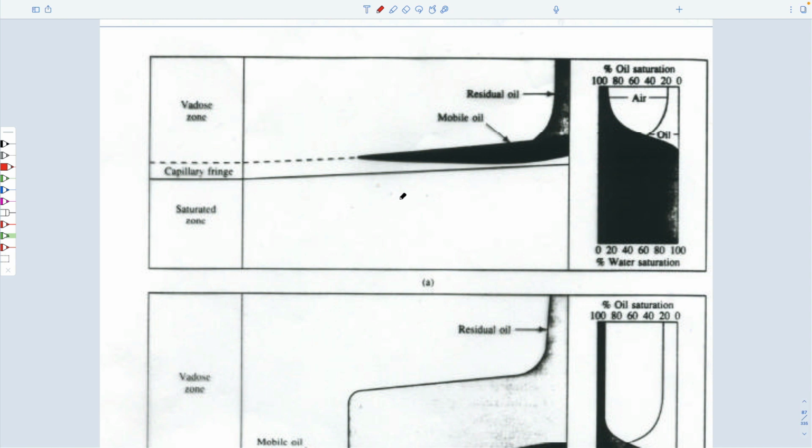So following on from this, I guess this is just an exposition of what you could imagine would happen in terms of smearing of LNAPLs again. If you get gasoline sitting on top of the water table, if the water table has an inclination to it, it will tend to spread laterally. If it spreads, then you could imagine that this would be the distribution of the different phases. Take any particular height that you want, and it would say something about it.